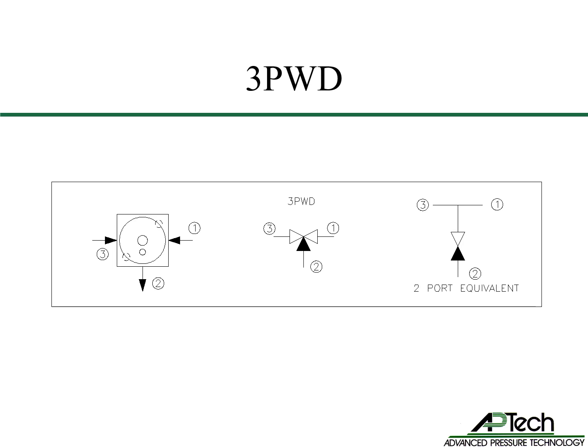There are 5 circles in the square. The large circle is the diaphragm chamber. The circle in the middle is the valve seat. The circle below the seat is a passage to the outlet port 2. The two circles in the bottom left-hand corner and top right-hand corner are the valve mounting holes.